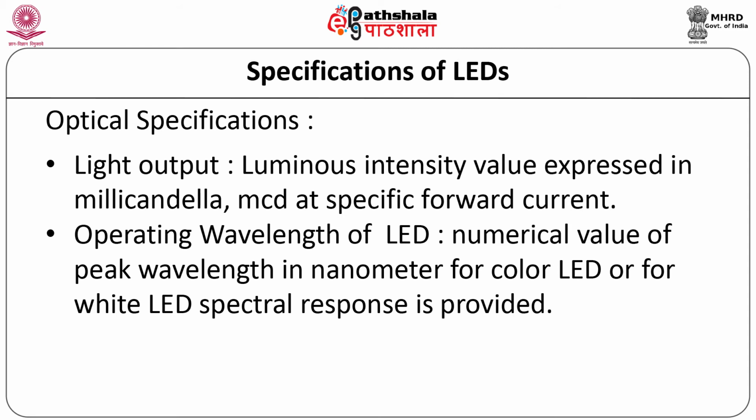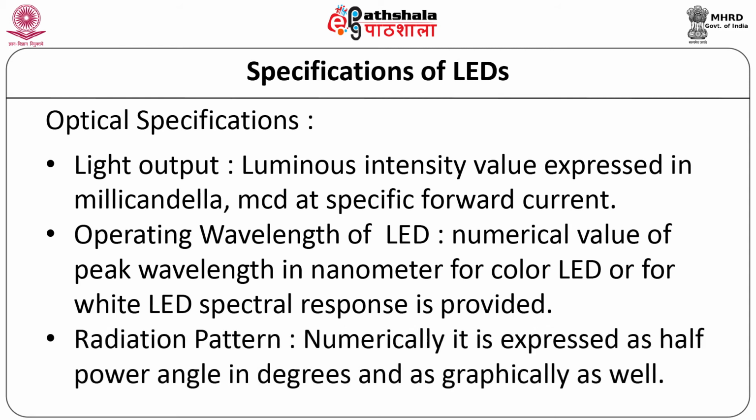In case of white LED, graphical spectral response of device is provided. Radiation pattern describes the relative intensity strength in any direction from the light source. Practically, light sources have various forms of radiation patterns based on different emission mechanisms, materials used for fabrication of sources, and manufacturing techniques. Datasheets of LED manufacturers provide radiation patterns in terms of relative intensity versus angle.